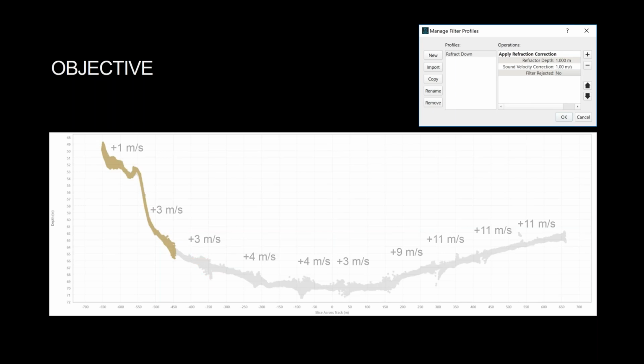And what's interesting is if you're watching closely, the number of clicks that it took to beat down each particular pass differs from left to right. In one case on the far right, you see it took 11 clicks with that 1 meter per second filter to flatten it, versus on the far left, it took only 1 click, 1 meter per second. So this is the part that's very subjective. There are tools out there to do this that are, I think, largely available in many, many hydrographic processing applications. But they all have this same approach where a user is looking at it and they're clicking a button until it's flat. And then you proceed through the whole data set. And that's the subjective part. Where this algorithm is quite interesting is it's objective. It will give you the same answer, independent of operator, time after time after time. And that's a big advantage in a lot of these types of algorithms in our industry.